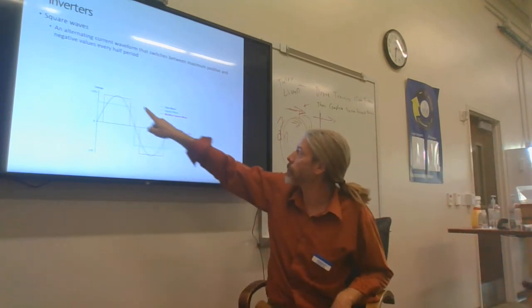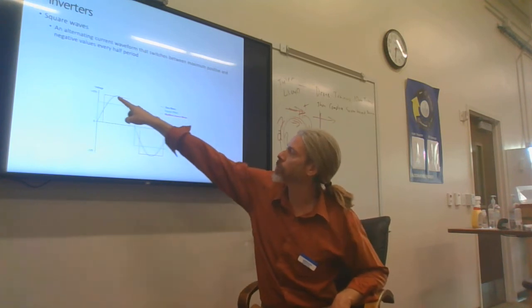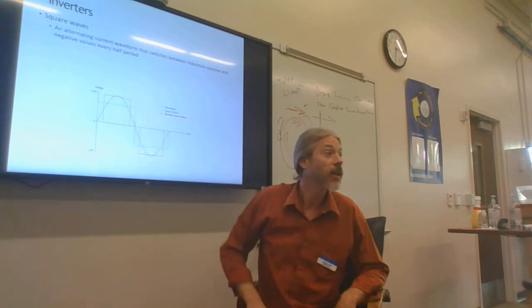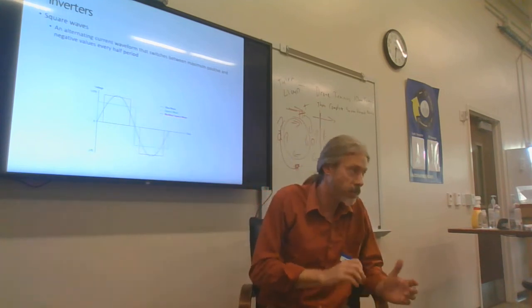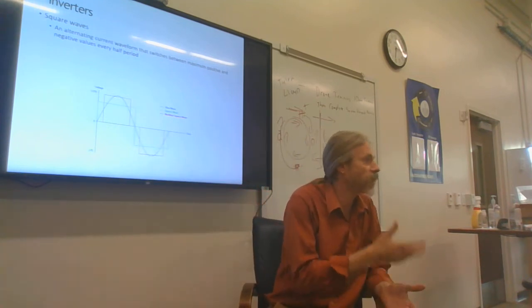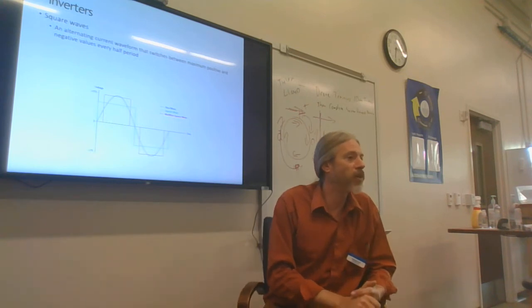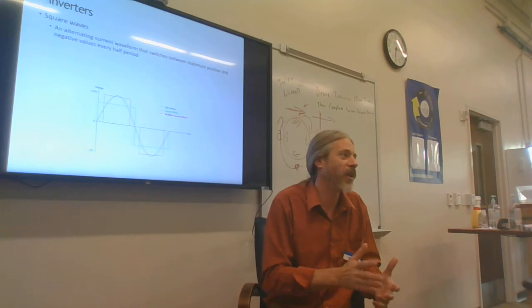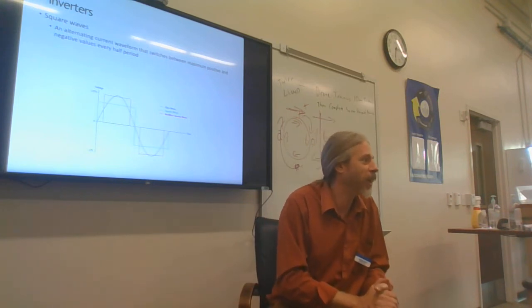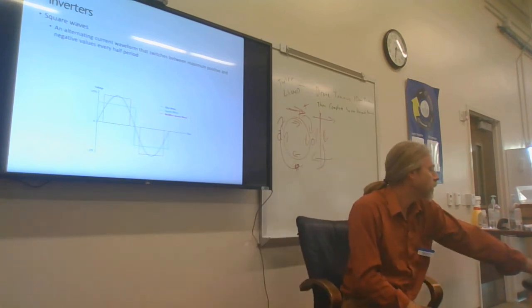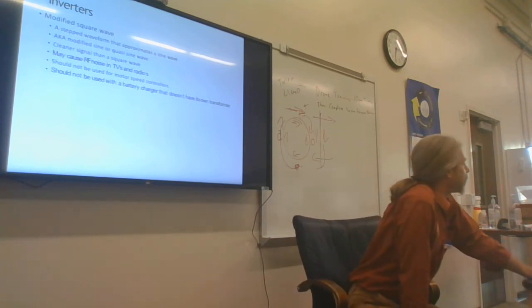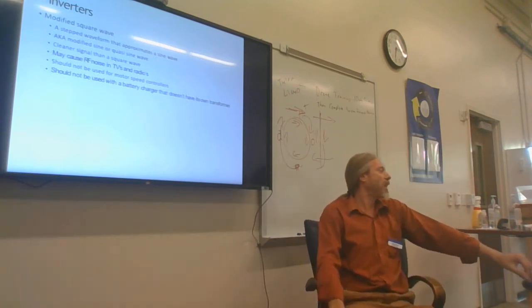See, this modified square wave still close to reaches the peak, but the sine wave really does have a higher peak, and that higher peak would mean more torque to get something started. So if your motor already struggled to get the load moving, man, that square wave might just burn that motor out.